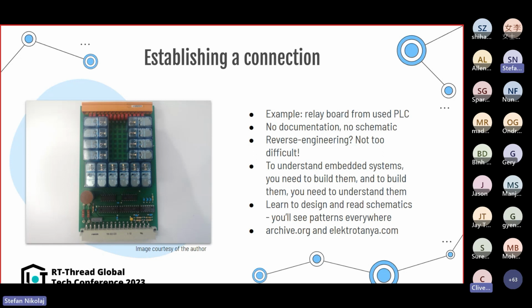Most relay drivers are the same, and the ICs used to drive the relays typically adhere to their datasheet circuits, with the only notable exception being the inclusion of a series RC network in this case. If you have experience driving relays with circuits and have previously connected a Z80 multiplex bus, you can readily comprehend the operational principles of this relay board.